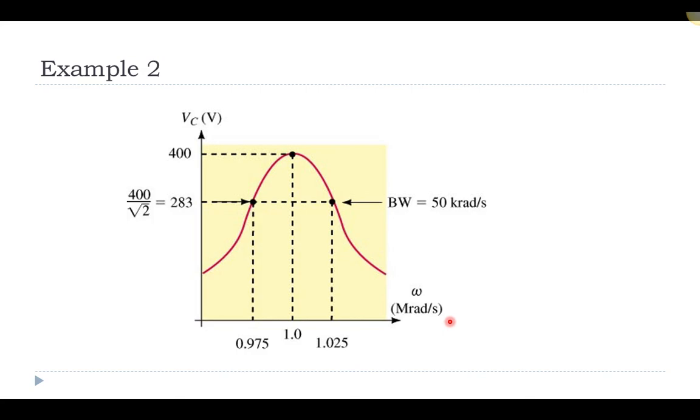So just keep in mind that from looking at series resonance, a lot of those calculations that we did in a little more detail, you can do those same things here with parallel resonance. So we could calculate the half-power frequencies and then plug those back in and figure out what the impedance is at those particular frequencies, and then we could certainly calculate the power as well.